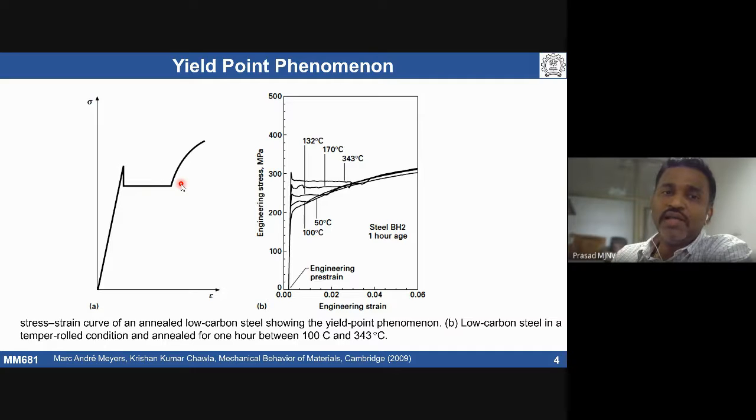By cold rolling, about 1 to 2% reduction, maximum 2% reduction. That basically ends somewhere here. The 2% is the amount of strain you are seeing, up to this lower yield point end. Depending on material composition, carbon content or nitrogen content, the amount can vary from 1 to 2%. So what you have to do is deform the fully annealed sheet up to about 2% reduction, and that can minimize the roughness problem we can see in the formed component.